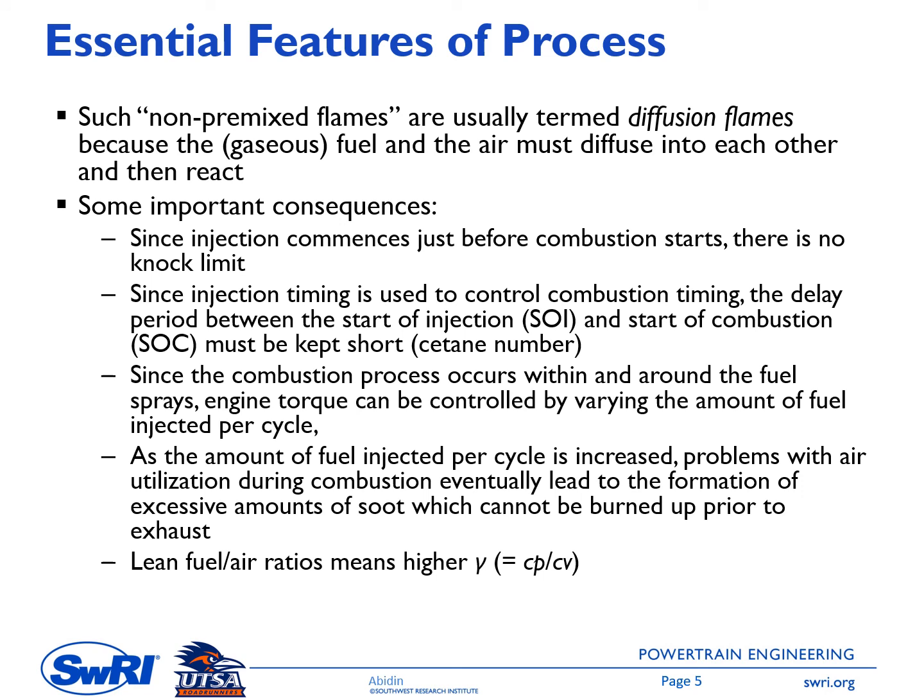In this case, it is very well known that this diesel combustion is called non-premix combustion, and sometimes it's also called a diffusion flame. This is because this gaseous fuel, the fuel that has vaporized and mixed with air, both must diffuse into each other and then react. That's why it's called diffusion flame. And there are some important consequences of this combustion characteristic.